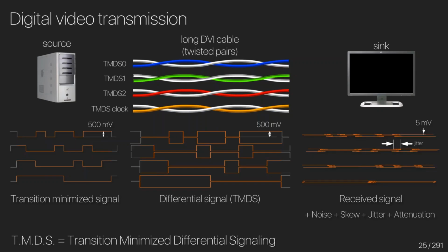A lot of these issues are factored into the design of DVI cables. They were particularly relevant when we were sending video signals over CAT cables using basic transmission technologies. HDBaseT solved a lot of those problems. However, we're seeing these problems occur again with HDMI 2.0 devices, and what you will notice with a lot of these problems is they increase when we increase the pixel clock frequency. A lot of them increase exponentially. So as we've gone to higher and higher pixel clock frequencies with HDMI 2.0, a lot of these problems are becoming more relevant. Despite having solutions for them in the past, they're sort of facts of physics. They're sort of baked into the technology, and there's no way we can ignore them.